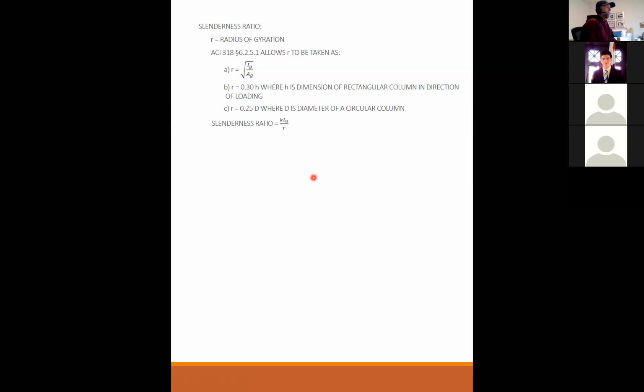That 15-foot-long column may very well be more slender than the column supporting the 71 freeway going over the 10 freeway that's like 120 feet up in the air, because that column is 8 feet in diameter. Does that make sense? It's how slender a column is in proportion to its effective length over the radius of gyration.